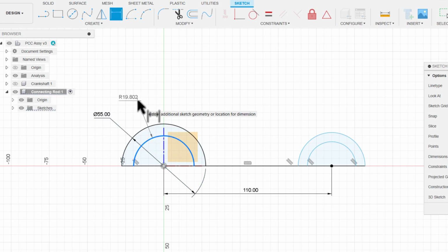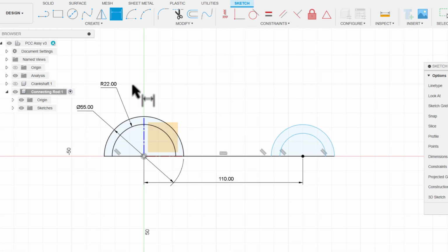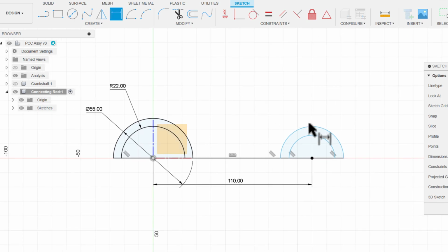And for the inner radius, 44 millimeters. So now it is again radius. Okay, if you want to convert, you can convert it, but let it be radius only. Let's say I am going to change that, I have the diameter only if you want to change it. Just enter the value divided by 2, then you will get the radius correct. Okay, so this is how you can use the relations inside the dialog box to give the dimensions.